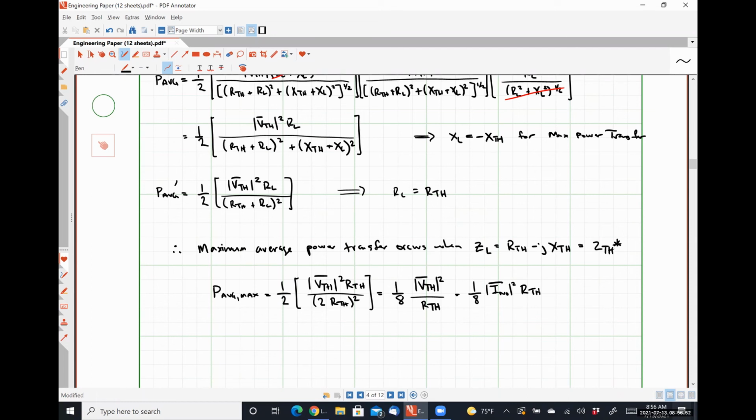So if you had a system that contained only a capacitor and only an inductor, no resistance whatsoever, you're asking what would happen. Right. So it depends, because you're going to have some inductive reactance and some capacitive reactance that you can combine together. It's literally combining the impedances.